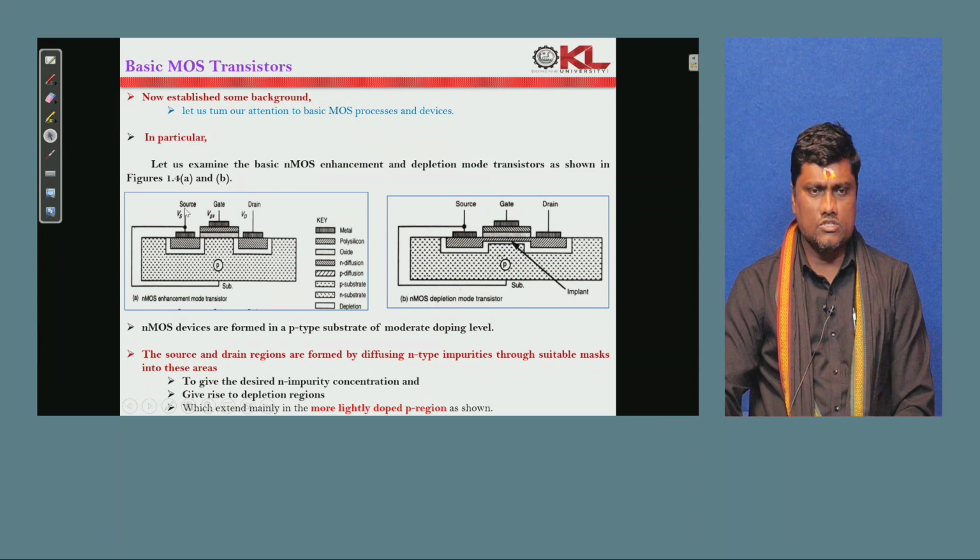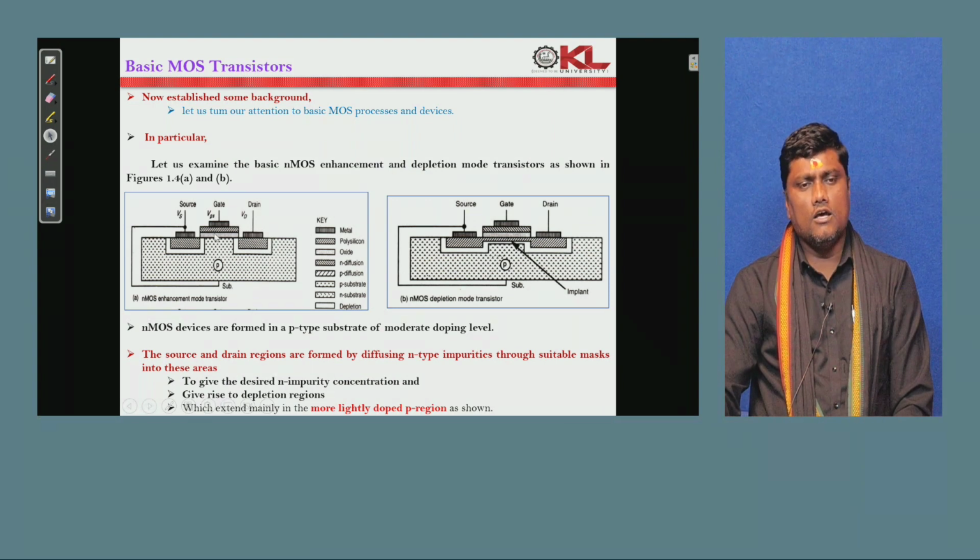The potential of the source is Vs and the potential of the drain is Vd, and between them we have the channel. At the bottom we have a substrate, which is also called the body, and above the channel we have an oxide layer made of silicon dielectric material, and above the dielectric we have the polysilicon metal, which provides the lead for the gate.